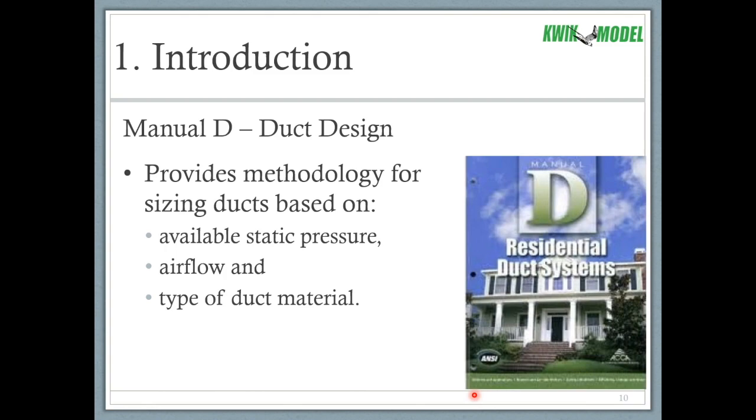And then the other thing that comes into play is the type of duct material. Is it flex duct? Is it rigid duct board? Is it sheet metal? Those all have different friction numbers according to the duct type, and that will change the size.